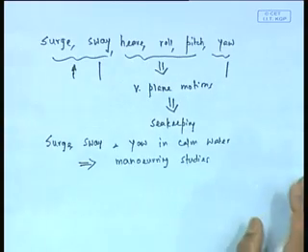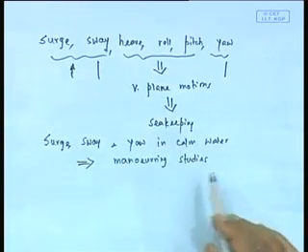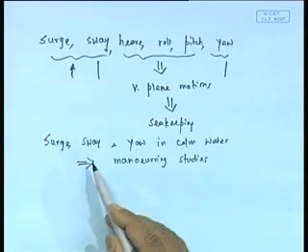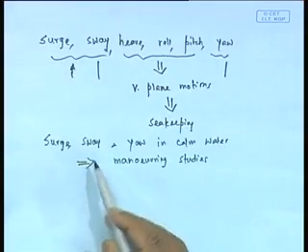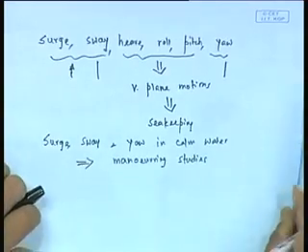So maneuvering studies are concerned with vehicle motion in the horizontal plane, that is surge, sway and yaw in calm water. Then immediately there is a question in mind: if it is in calm water, where is the force that is causing the motion in the yaw and sway directions? Well, surge, okay, it's a resistance. Now I will answer this question, and this is exactly the crux of the matter.